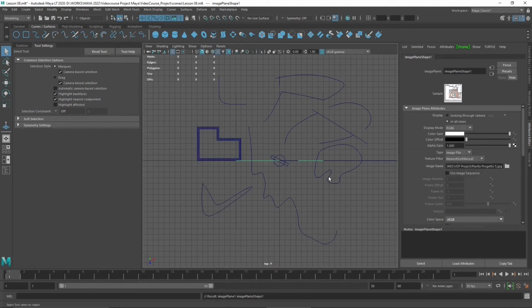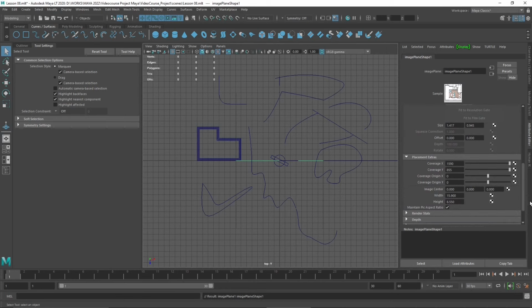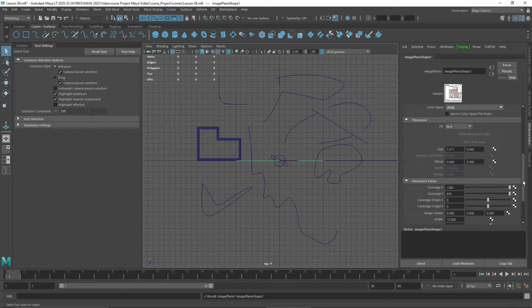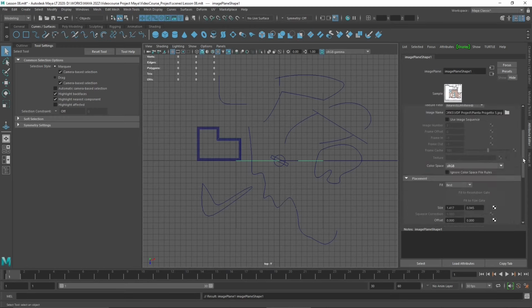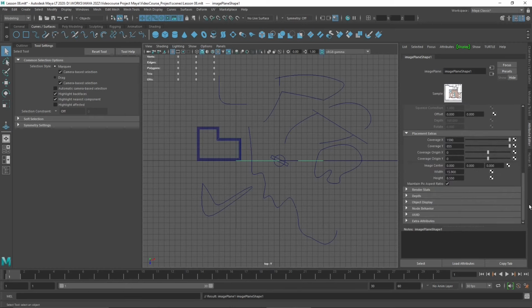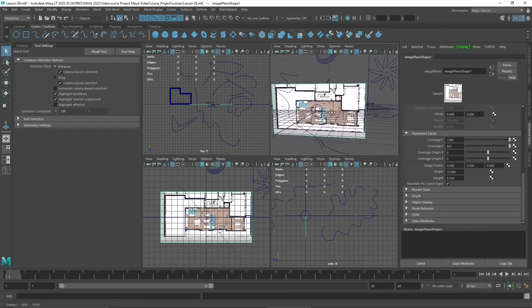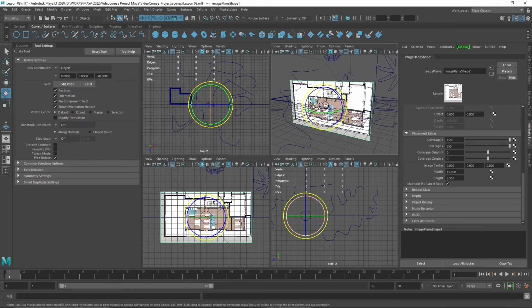It's an architectural project. So if I place that, you can see that I am in the wrong view, because I see this from the top and it's looking just like a simple plane. So I need to change the orientation or the rotation or something that is going to make me see this in the top view, because usually when you create architecture, you should be on the top view. If you create graphic design, you can be in other vertical views like front view or side view.